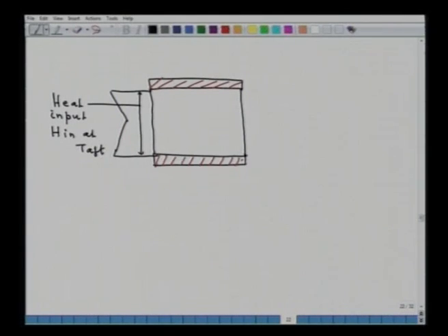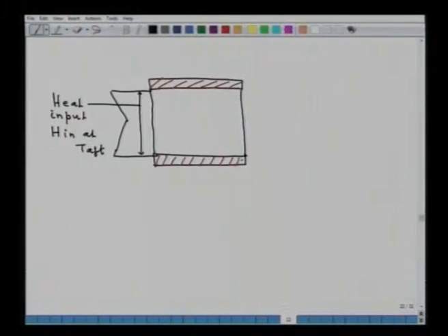Now, as we have done in problems on combustion and heat utilization and heat transfer so on, we have seen that a fraction of the heat is lost with the products of combustion, and this is a major fraction. So, this heat which is the HPOC, which is lost at temperature TPOC.